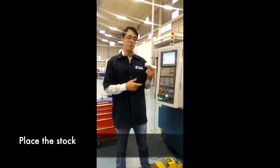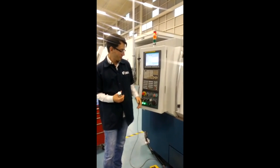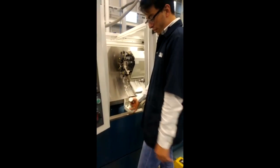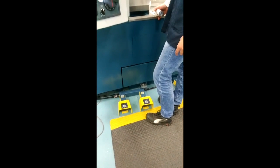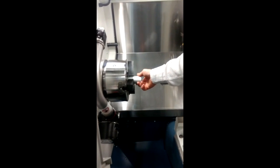Process, we have to mount our stock. For that, we need to open the door, change to MPG, and proceed to mount the piece. For that, we have two pedals. The first one is to close, and the right one is to open our jaws. Put the piece in the jaw, and then press the pedal.